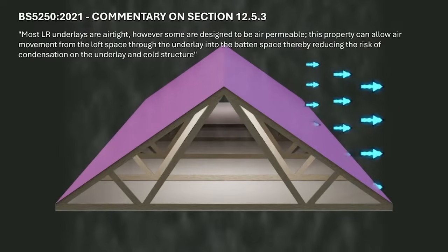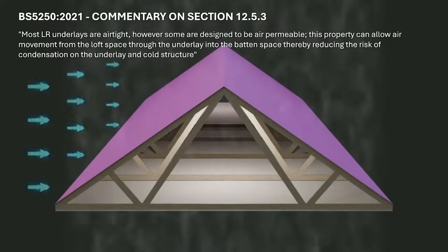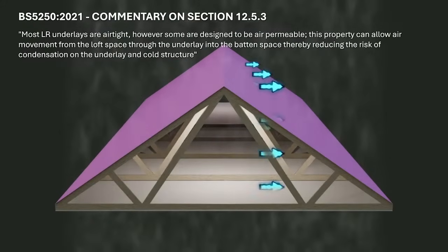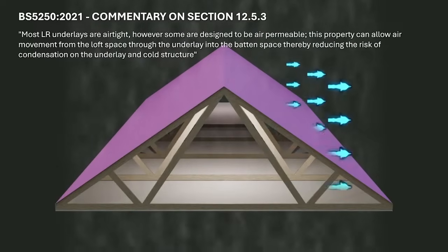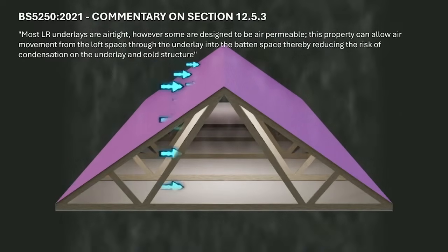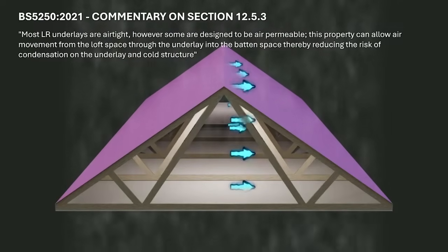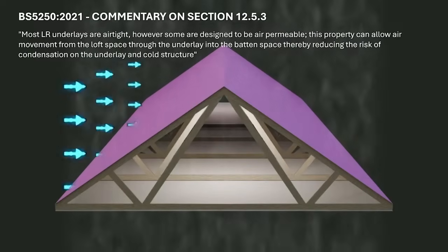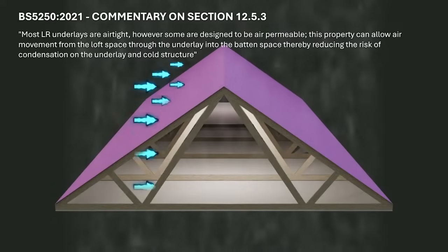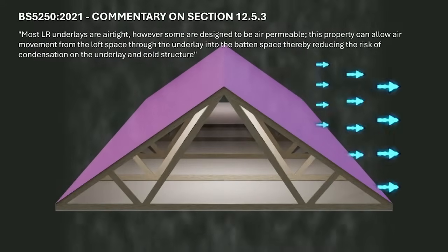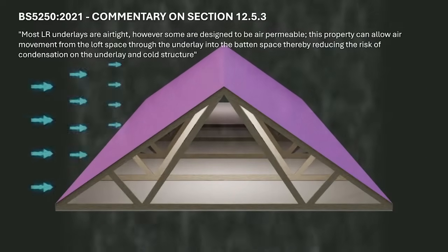Air permeable or air open underlays provide, in the opinion of the BBA, a significant additional mechanism for water vapour egress by convection, and therefore sometimes have fewer restrictions on their use. For example, some air-open membranes may not require the use of a well-sealed ceiling or vapour control layer. The requirements might vary between the membranes though, so it's important designers and installers are aware of these differences. Whilst it may seem that one type of LR membrane can simply be swapped for another, and indeed this may arguably be true of airtight LR underlays where ventilation is used, for completely non-ventilated constructions the picture is more complex.